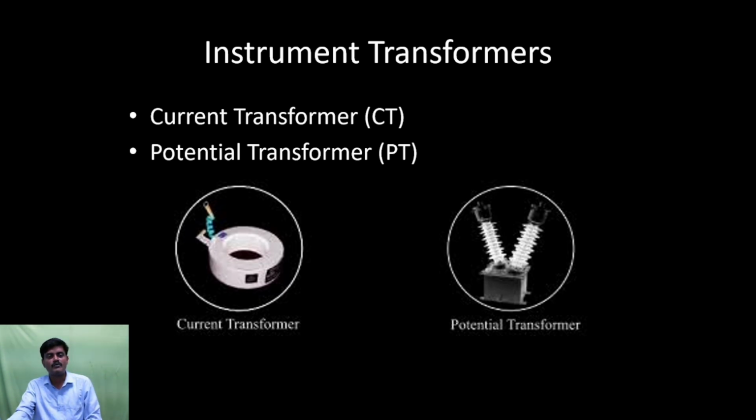So what is the power I am getting? What is the power of the system? For that we need the current value and also the voltage value. Then only I can measure the power value. So in order to measure the current value, on the conductor I am placing one transformer. On the conductor we have the flux lines. That flux is linked to the secondary of the transformer. Accordingly it gives the value.